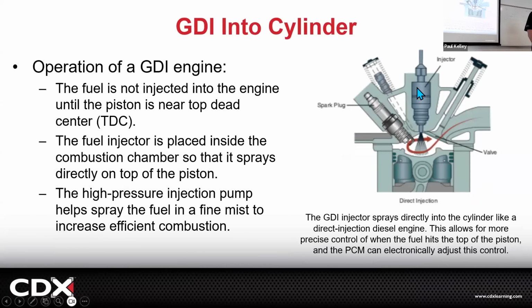This injector right here is literally put into your cylinder. So it's a much larger injector. Here's the main problem. How much compression did your cars make when we did those compression tests? 130, 150, 175, 180. All right, if your fuel pressure is 50 and your compression is 180 and you open up your injector into the cylinder, what are you going to win? Your 50 psi of fuel pressure or your 180 of cylinder pressure?